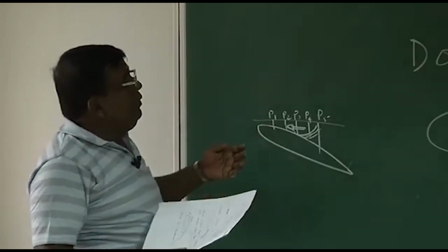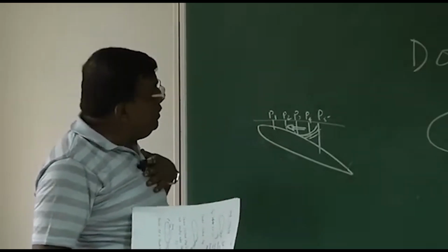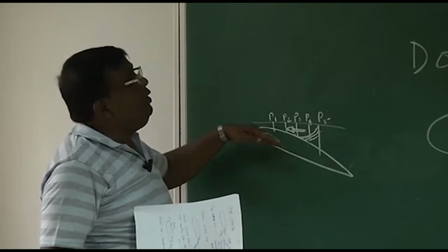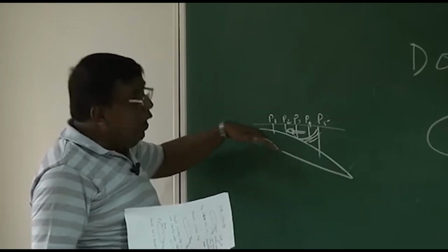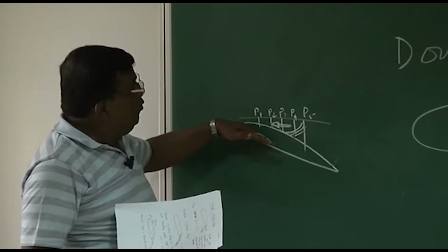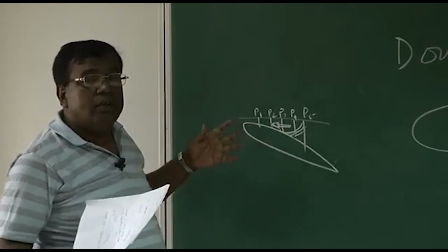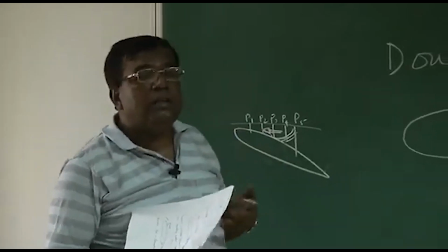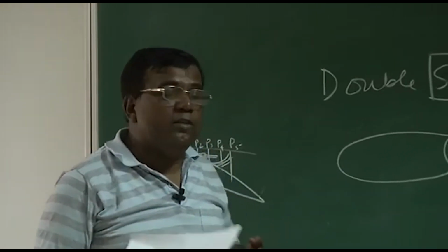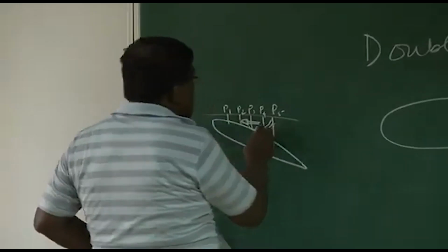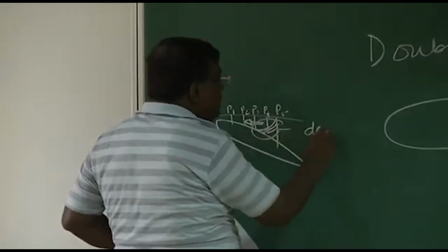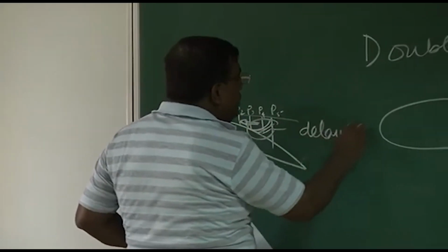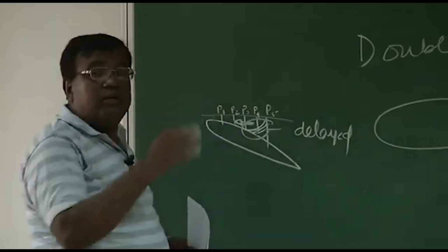In the language of flight mechanics, that means I will not be able to use beyond that angle where flow separation starts. So the flight mechanics man will ask a question: do I have a mechanism to ensure that this separation is delayed? That is, I can use a further angle of the flap.